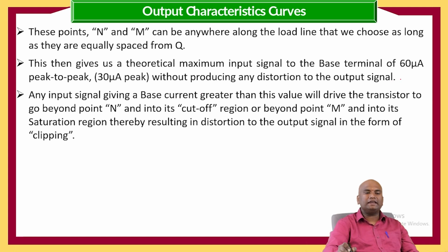And any input signal giving a base current greater than this value will drive the transistor to go beyond point N and into its cutoff region, or beyond point M and into its saturation region, thereby resulting in the output signal in the form of clipping.